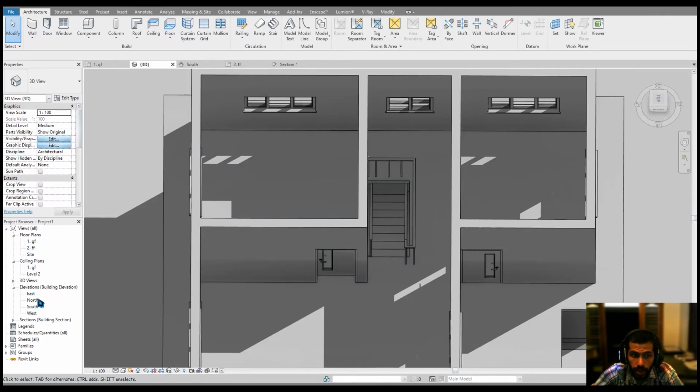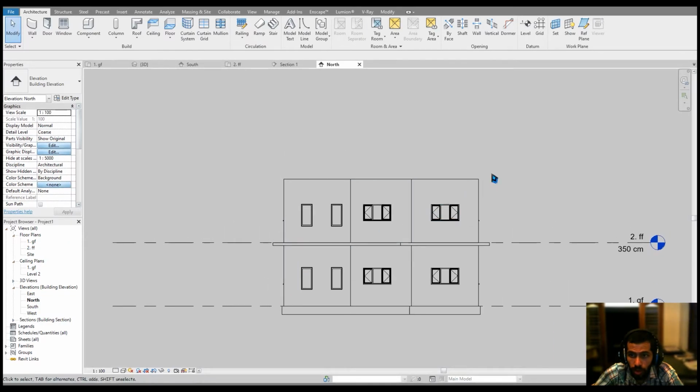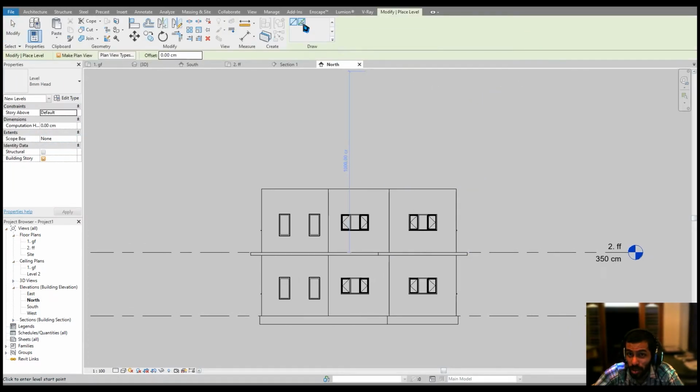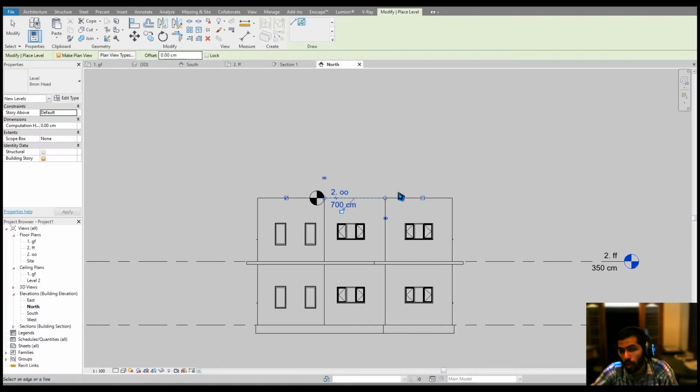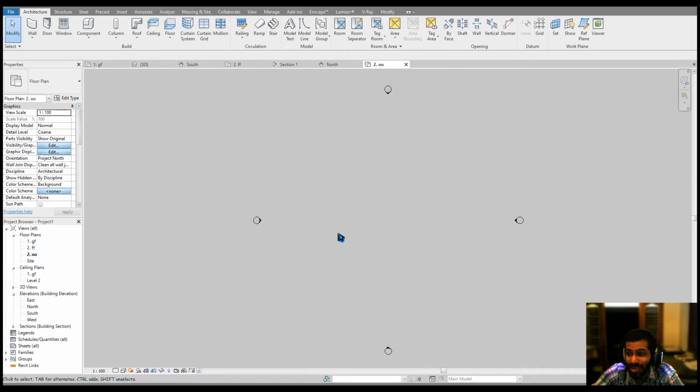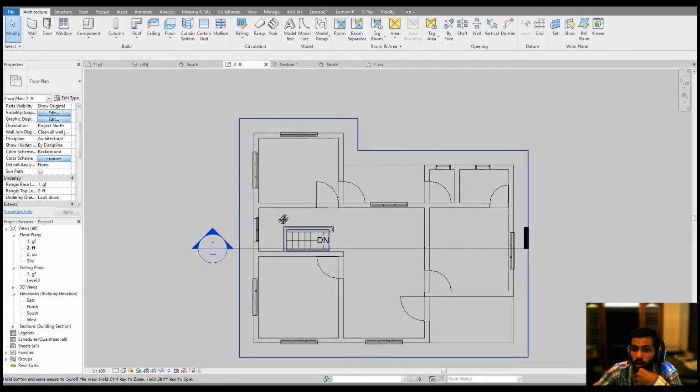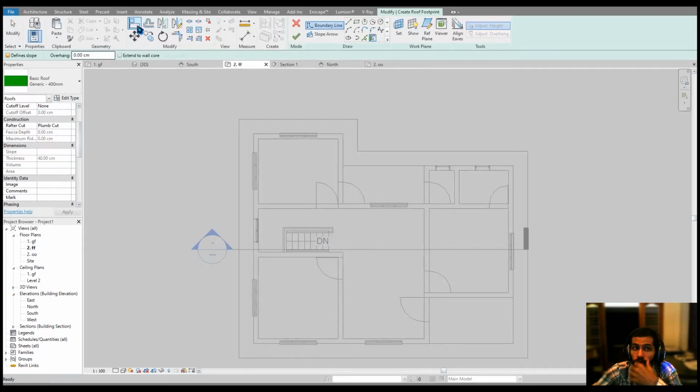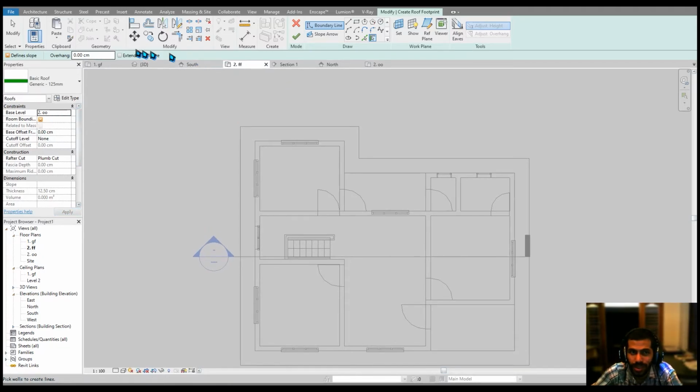Finally, let's try to place the roof right in here. In order to place a roof, I like to have a level which is made by using pick line right on top of here. So the roof will be in level 00. If you get into 00, maybe you can't see anything. If the object in the level is not visible, you have two options here. The first is to get into the first floor and make use of roof and change the thickness here, and the roof shall go into the third level 00 anyways.